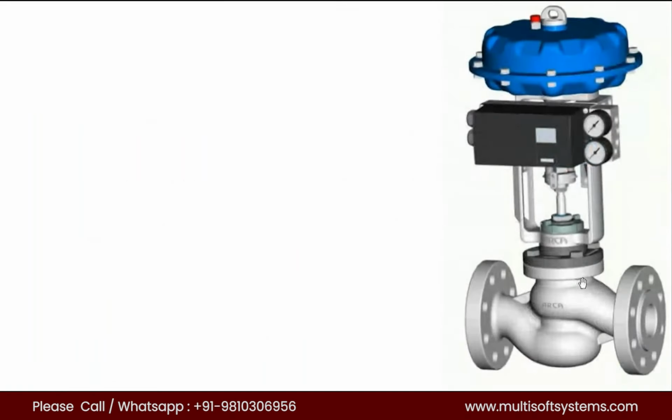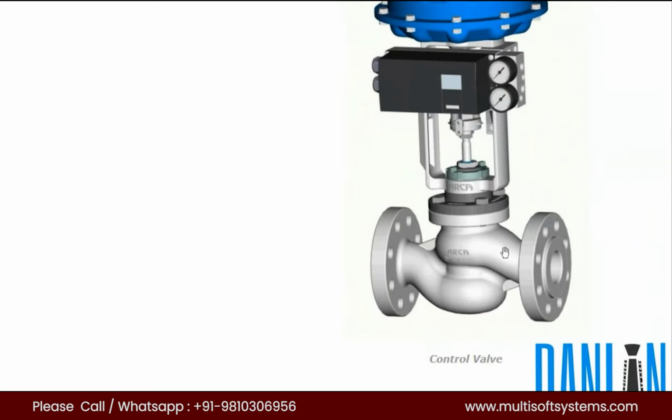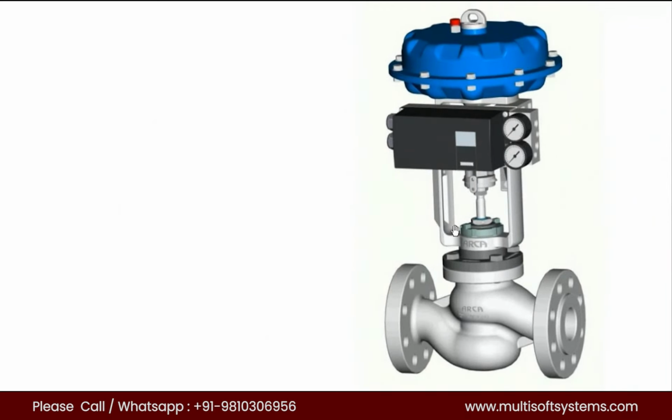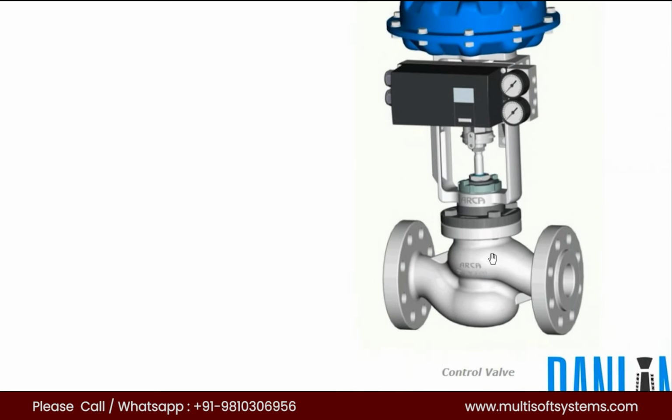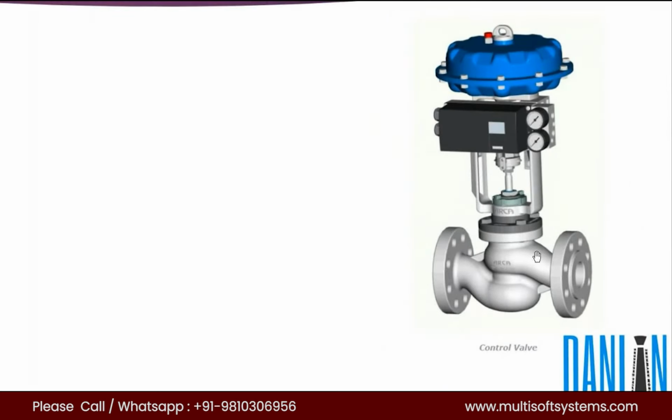And then control valve means, like the globe valve, we have the motor and actuator, and most probably this control valve we are using for the pressure drop. That means in the vent line, if you want to reduce the pressure from 2500 rating to 150 rating, we can use this control valve. It's like a globe valve presentation only. In that, the motor, actuator, everything will be fitted under this arrangement.